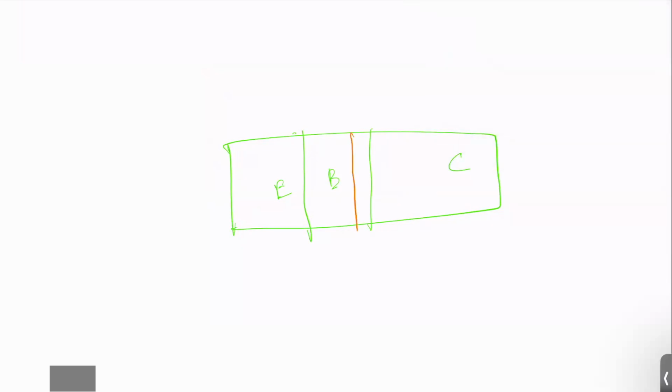Imagine case A, and now we're going to go to case B, where you have a wider depletion region. You can immediately see that usable space in the base has reduced. If you have a wider depletion region in the base collector junction, you have a lower usable region in the base, so a lower effective width in the base.